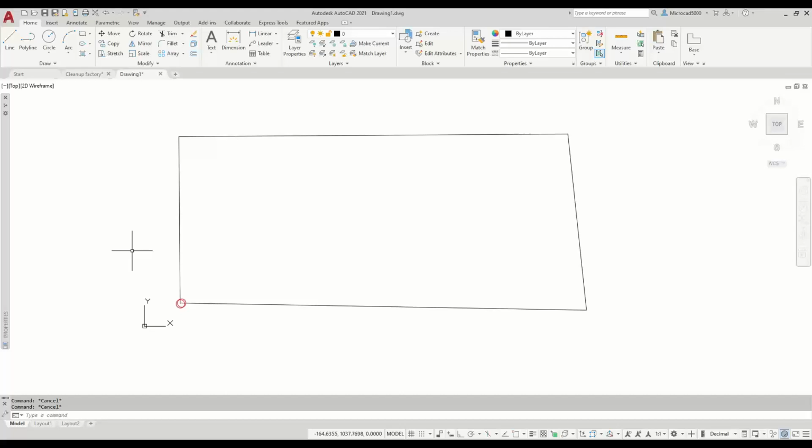Now this is a very simple shape, but you might have a complex area that you want to hatch in, and it just won't hatch it in. Anyway, a regen will clear those red marks off the screen. Now if you read the help files, it says it's got to be a closed shape. If you go onto the Autodesk website, it's got to be a closed shape.